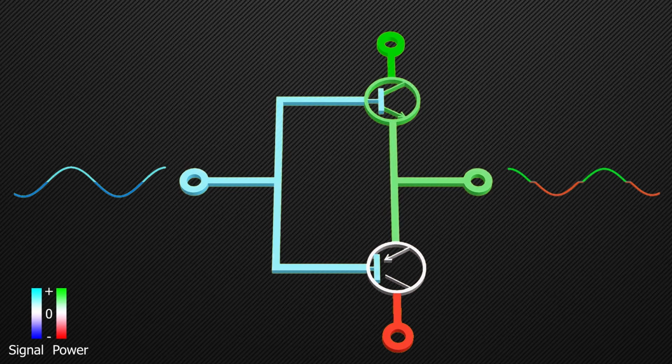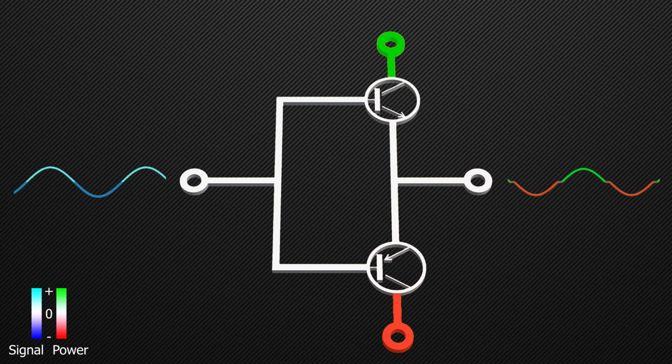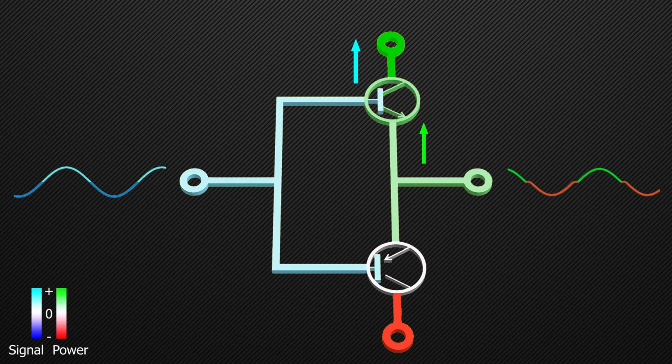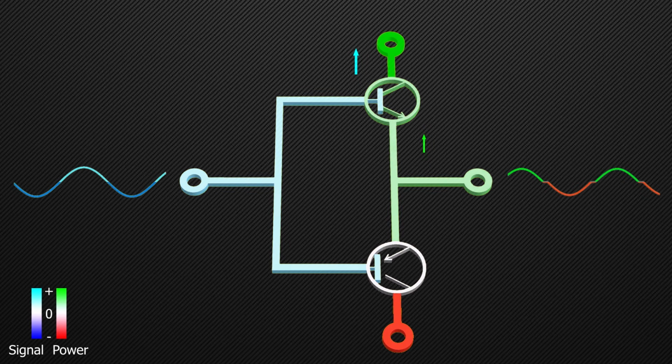Now, you would know that a transistor requires 0.7 volts between base and emitter to turn on. Thus, during the positive cycle, until the voltage at the base is above the cutoff voltage, the transistor is in its off state, and the output voltage is 0. And when the voltage at the base increases above the cutoff voltage, the voltage at the emitter starts to increase, following the base voltage, until it reduces to below the cutoff voltage.